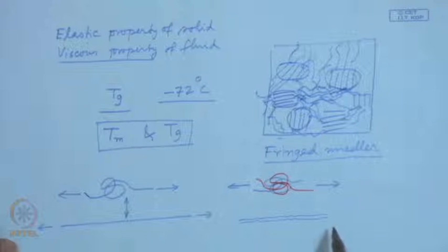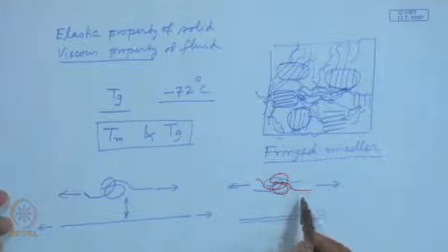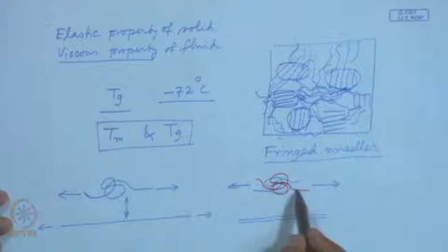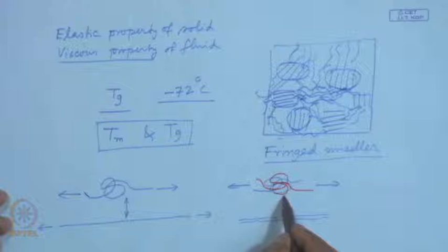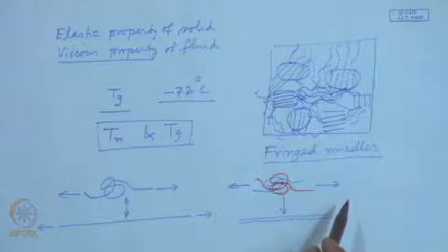That depends on the extent of deformation, to what extent it is deformed, to what elongation it is stressed. On release of the stress, it may not come back to its original configuration. If there is permanent slippage of, say, this red molecule over this blue molecule, it cannot come back to the original or initial morphology.